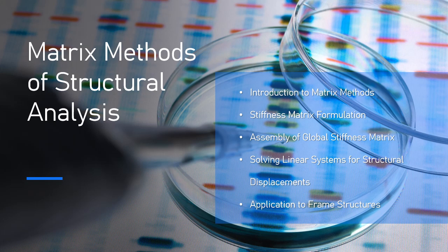3.1. Key characteristics of frame structures. In a typical 2D frame structure, each element, e.g., beam or column, has 6 degrees of freedom, 3 per node: 2 translational DOFs, movement in the x and y directions, and 1 rotational DOF, rotation about the z-axis, at each node.